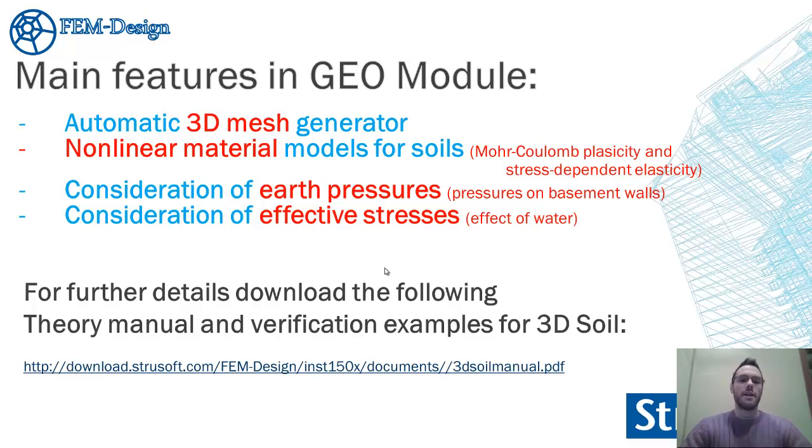So the second main feature, as I mentioned earlier, is the nonlinear material models for the soil. So besides the linear material model, we have the classical Mohr Coulomb plasticity in FEM-Design, and a stress-dependent elasticity is also available. It's another nonlinearity in FEM-Design.